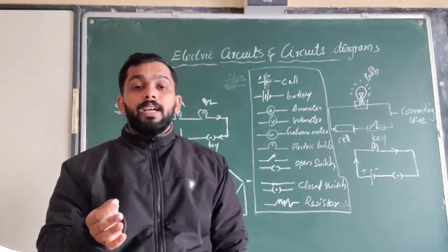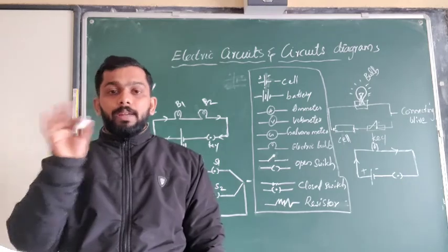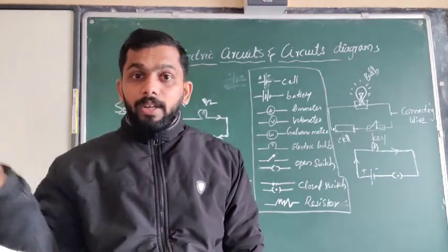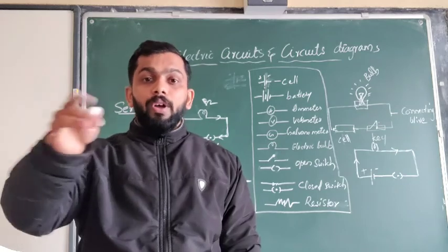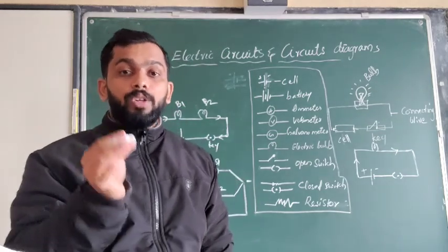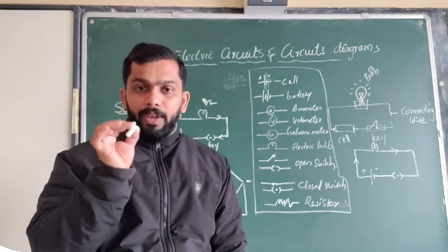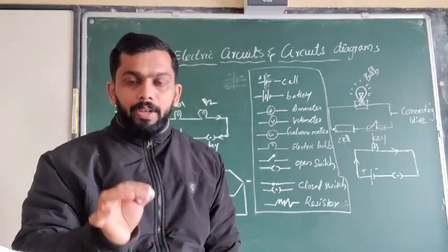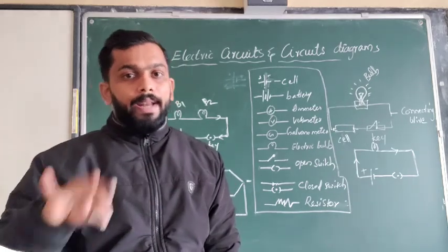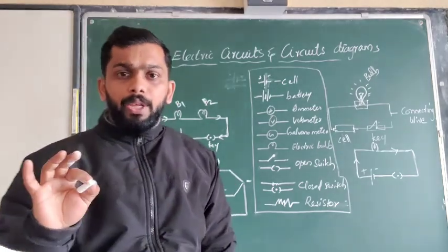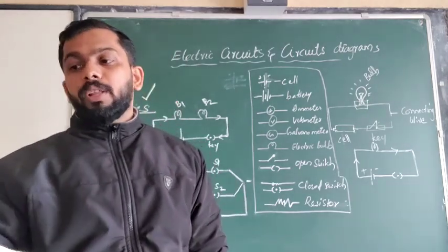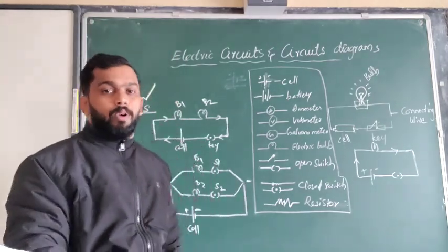And another thing is that if there is a complaint in the fan, when we switch on the fan it will not work, but the other devices will be working. So very easily we can find out which device is damaged and we can repair it very fast. That's why we use parallel connection in our home wiring, and for all devices we normally use parallel connection.